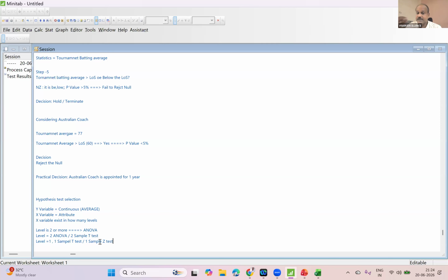If changing the primer can significantly change the adhesive strength of the paint, you know what I will do? I will find out exactly which primer leads to maximum adhesive strength. After that, I will only use that primer and stop purchasing primers from other sources. Earlier, my belief was that I can use all primers in the painting process. But after doing a little research, I understand I cannot use all primers blindly. I really have to find out whether the primer has a significant effect on the adhesive strength.